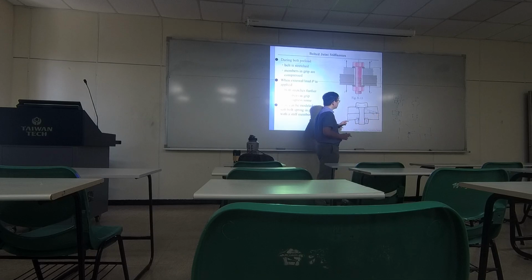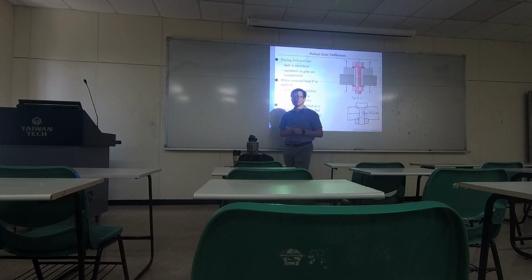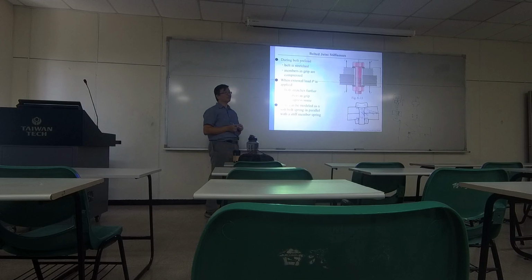And on the other hand, when you try to clamp whatever is in the middle, the bolt itself is actually being lengthened. As you tighten the screw, the bolt is going to be lengthened. Basically, there will be a tensile force at the middle. Okay? So this is how you can truly have a good clamp of the object in the middle.